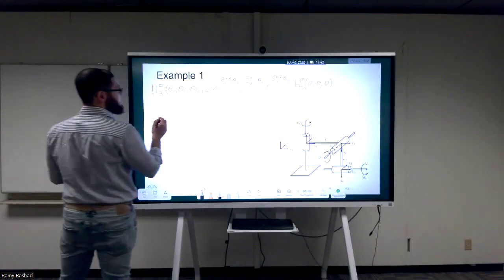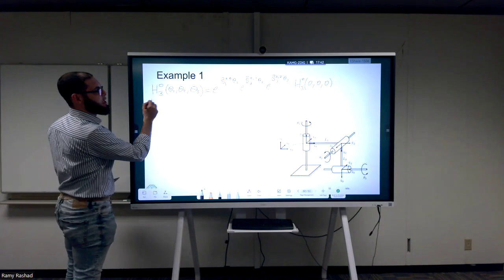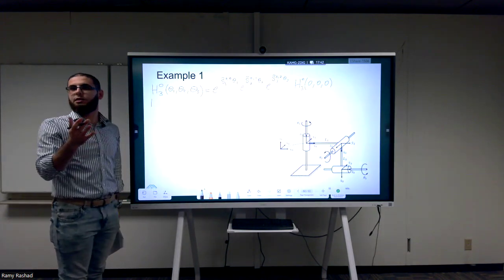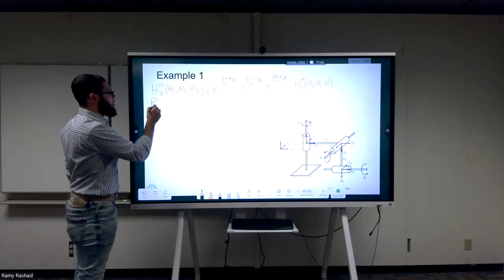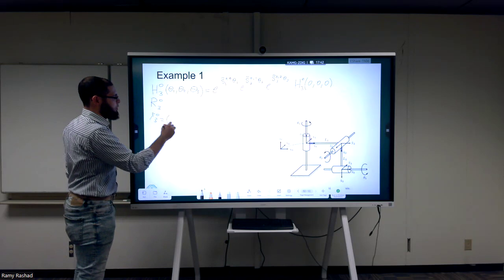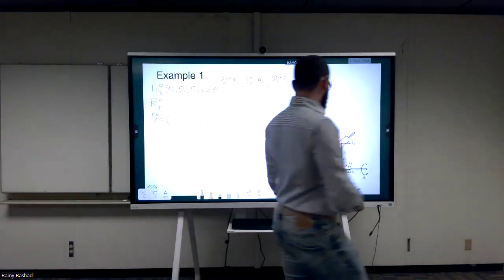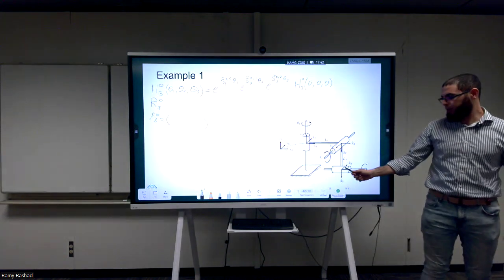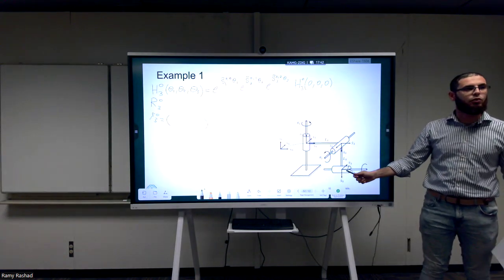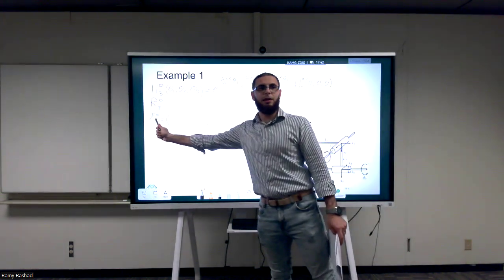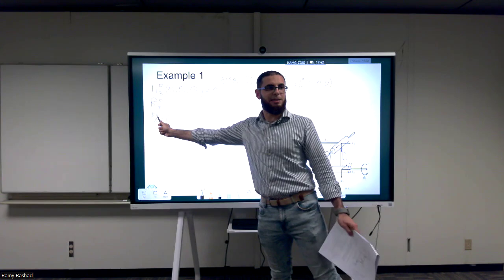So the first thing, let's calculate H3 with respect to 0 in the home configuration. And the H is nothing else than two components, right? The R3 with respect to 0 and the psi of 3 with respect to 0. Let's start with the second one, with the psi. So how can I reach this point from this frame? Because the psi 3, 0, what does it mean? It means the origin of frame number 3 as seen from, or expressed in, the 0 frame.